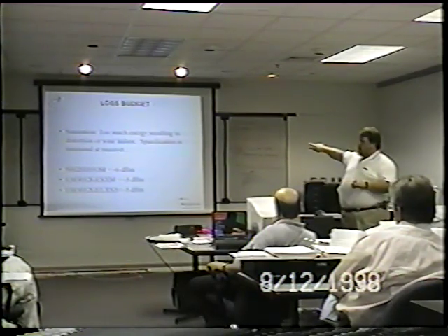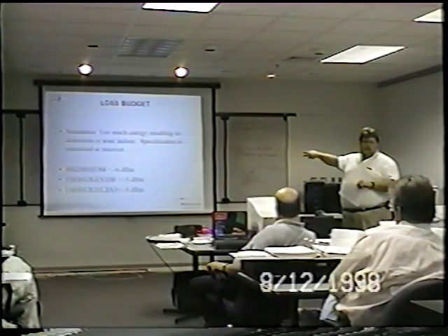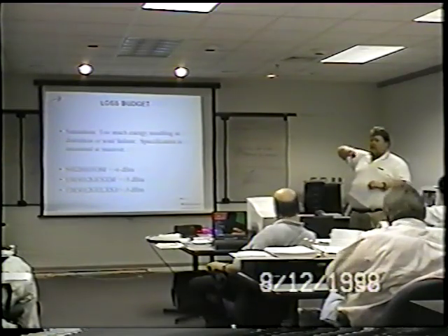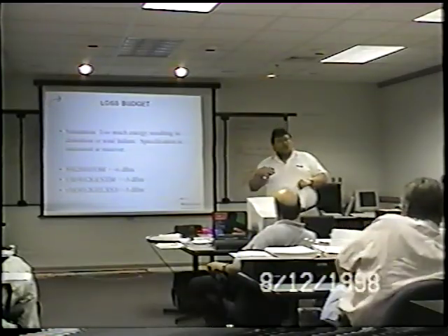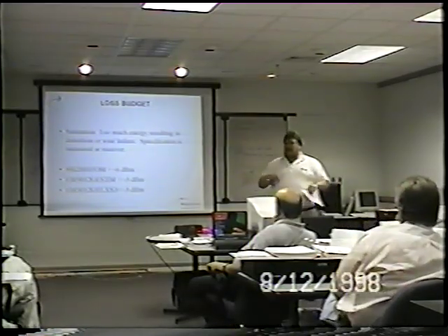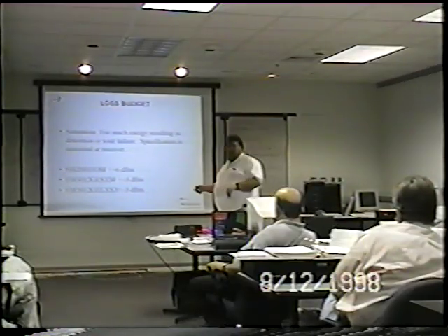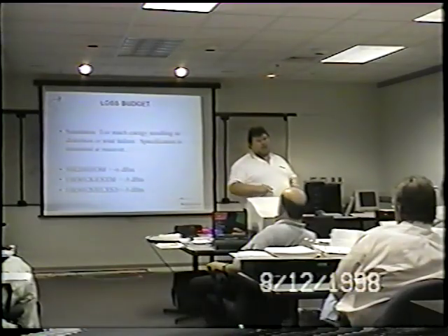Now, keep in mind that saturation can be the number one killer to evaluations. If you're ordering up equipment, specified equipment to go into an installed site that might be 30 miles apart, the customer all of a sudden wants to see this working on the bench, side by side. To take an S3 optic with a 6-foot jumper and pump it into a receiver right beside it, that's the formula for trouble every time.